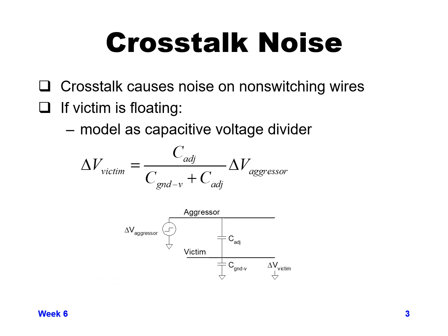So I just went through how crosstalk affects delay. Now I'm going to talk about how crosstalk affects noise. There are two different possible ways that crosstalk noise happens. Crosstalk, like I said before, matters to us for noise on a wire that's not switching. Delay matters when two wires are switching at the same time. Noise matters when one wire was supposed to not be switching and the other one was switching.